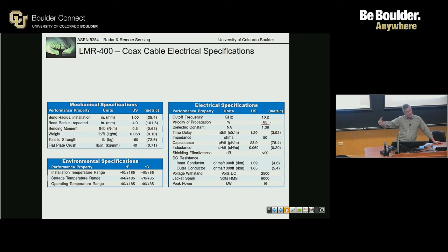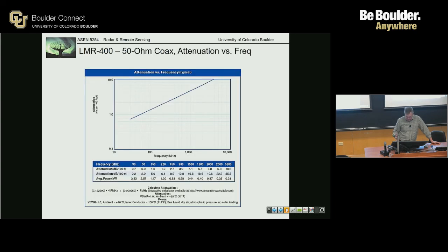You'll need to account for that in your timing. Usually there's an offset that you add to a system to account for propagation losses, a percent of the free-space propagation path, the speed of the wave as it goes through cables.